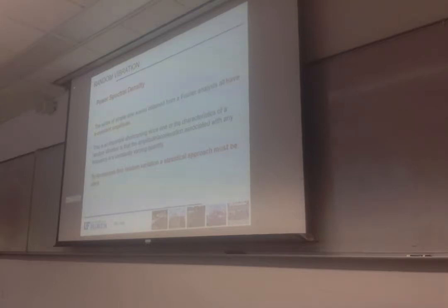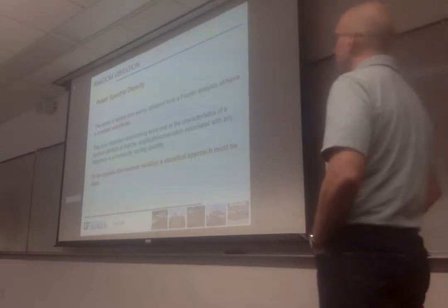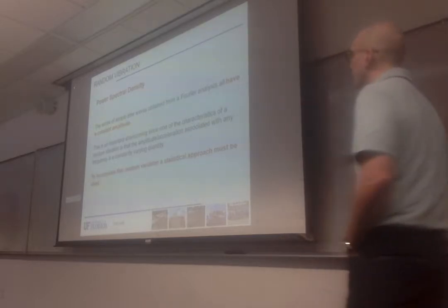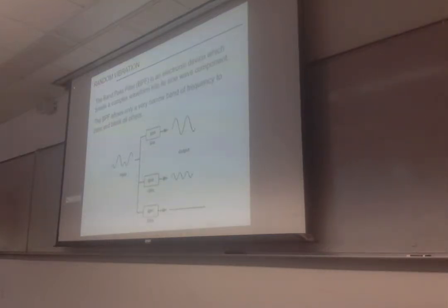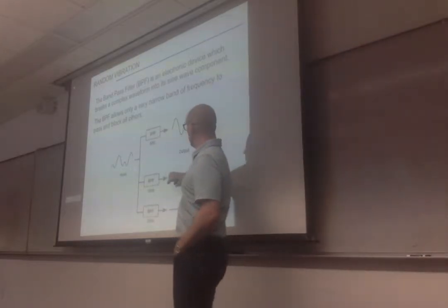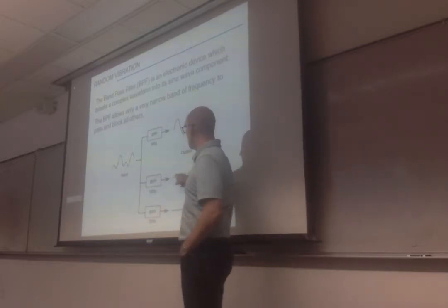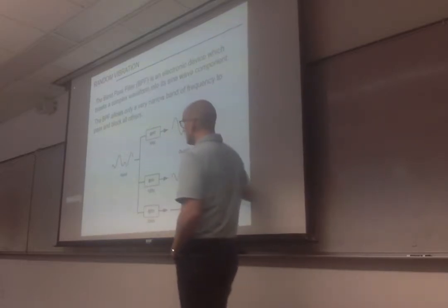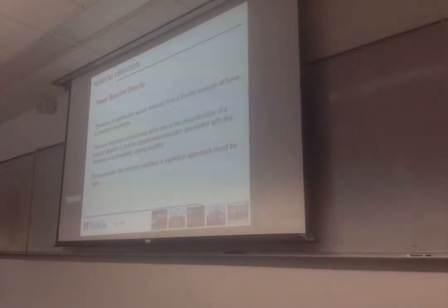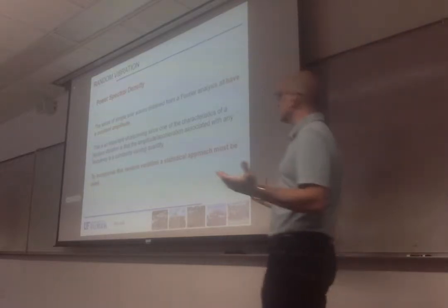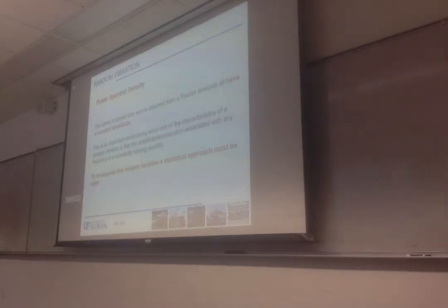So one thing that happens as an inherent property of the Fourier analysis is that the series of simple sine waves coming out, like this, all have a constant amplitude. So that means you're going to have something that does not vary. That means the maximum acceleration or maximum amplitude is going to be constant all the time. So this is an important shortcoming that is mentioned here, because for random vibration, the deal is that for a certain vibration, these peaks can go up and down, they can vary.